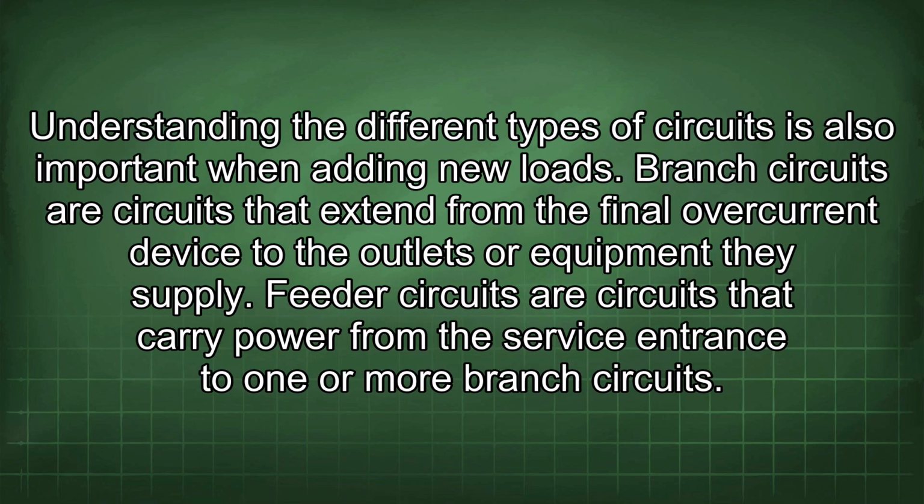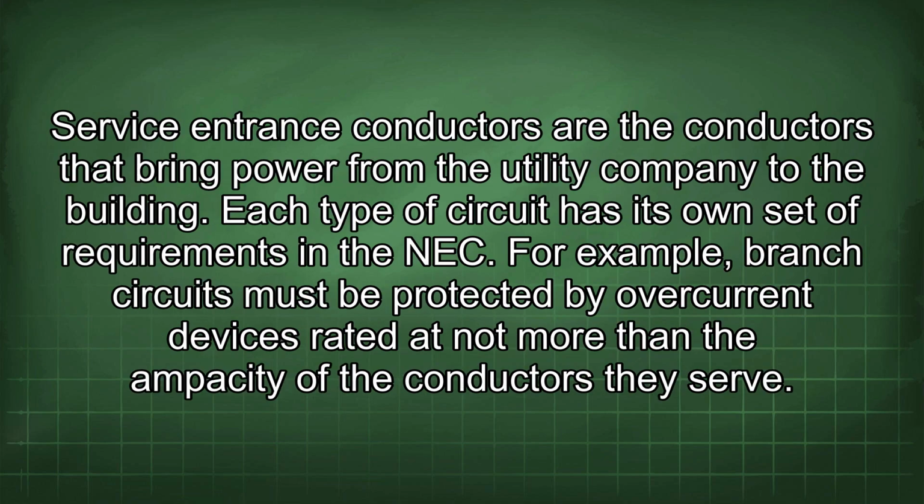Understanding the different types of circuits is also important when adding new loads. Branch circuits are circuits that extend from the final overcurrent device to the outlets or equipment they supply. Feeder circuits are circuits that carry power from the service entrance to one or more branch circuits. Service entrance conductors are the conductors that bring power from the utility company to the building. Each type of circuit has its own set of requirements in the NEC.